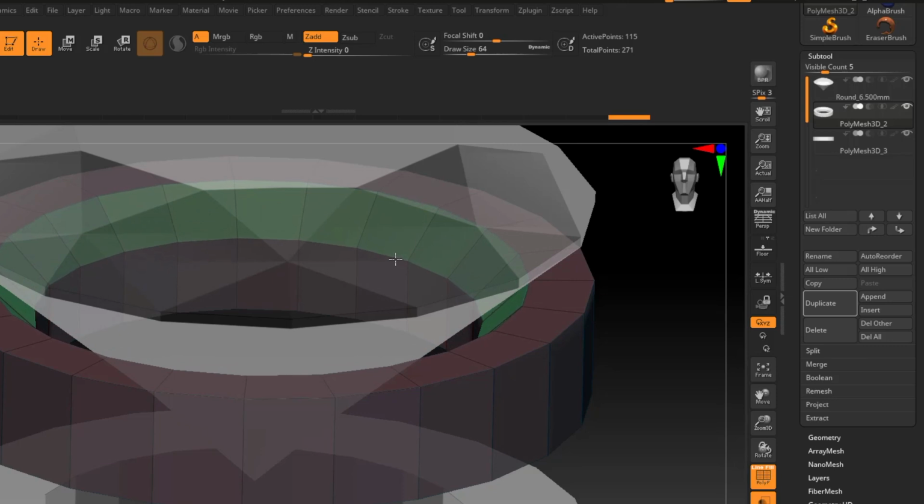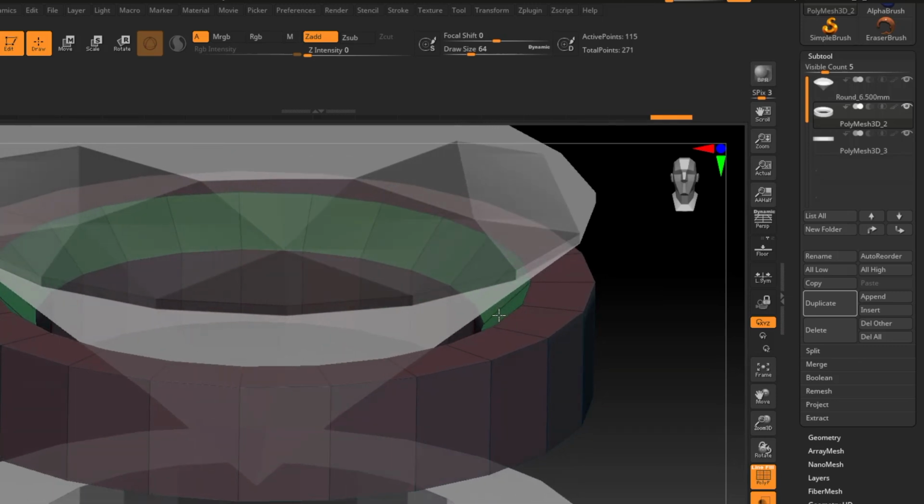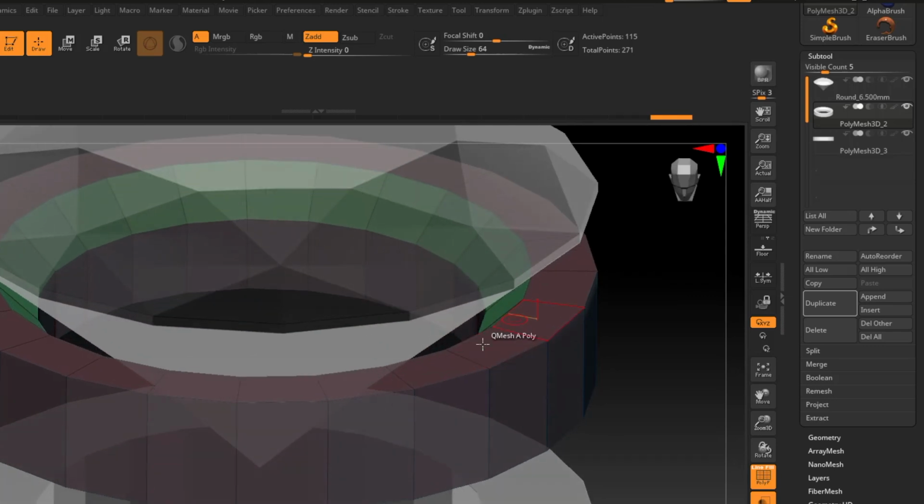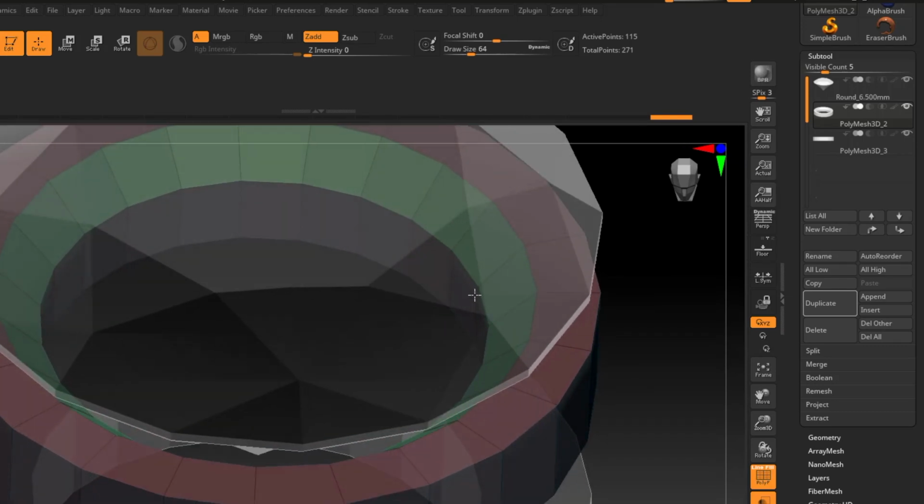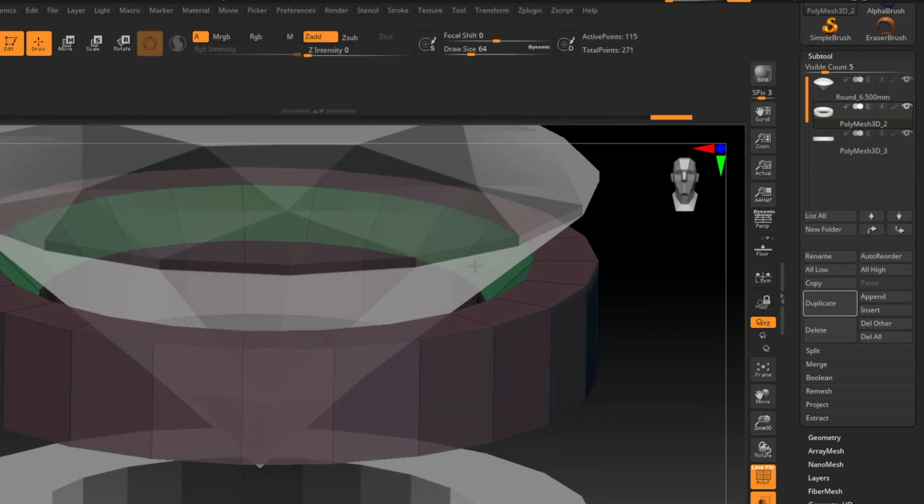So now, when I hover over this edge and left click and drag, it's going to create that bevel there. And you can see the edge coming away from the stone. That's exactly what we want. And it doesn't have to line up perfectly. You can have a gap there, that's actually preferred, because the stone is not actually going to be sitting on this bevel. It's going to be held up by the prongs. But it will create a bit of light that's able to get through the metal and the stone. And a bevel like that is pretty much all you need.